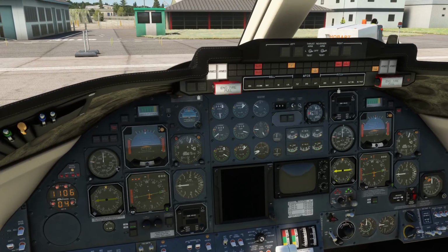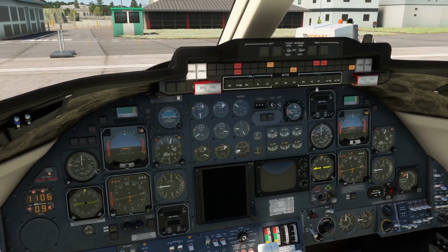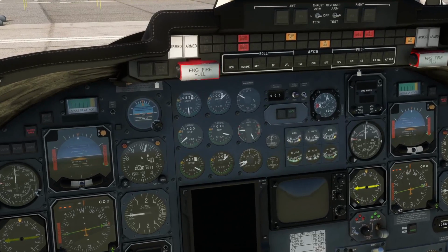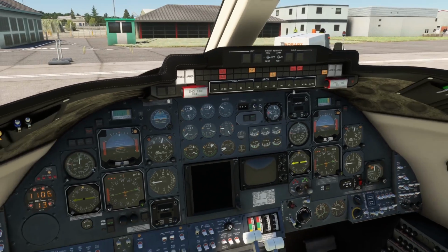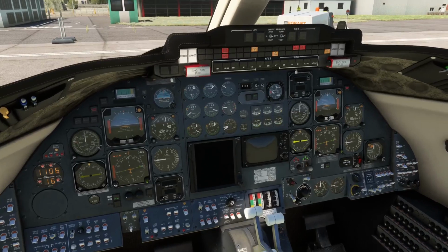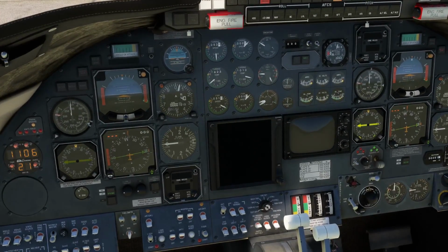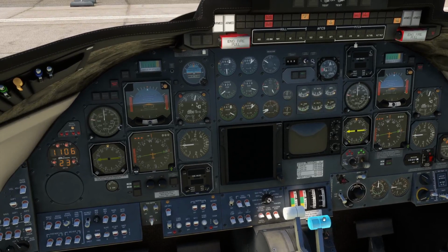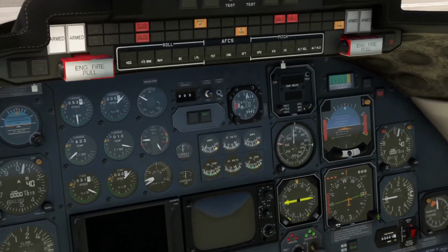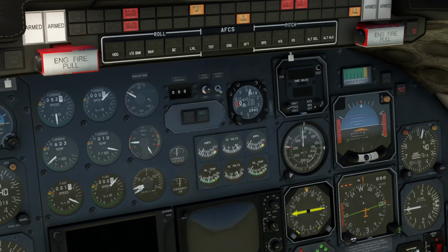And also the battery itself, if it's below 13 volts, you won't be able to turn it on as well. It's not modeled, but in reality, yes, a very low voltage state in the battery would be detected by a sensor that it's below 13 volts, or is it 13 or 16? Anyway, a low voltage state, and it just won't complete the circuit if that's the case. It's a protection, a way of making sure that you don't try and operate the aircraft with insufficient charge in one of the batteries.